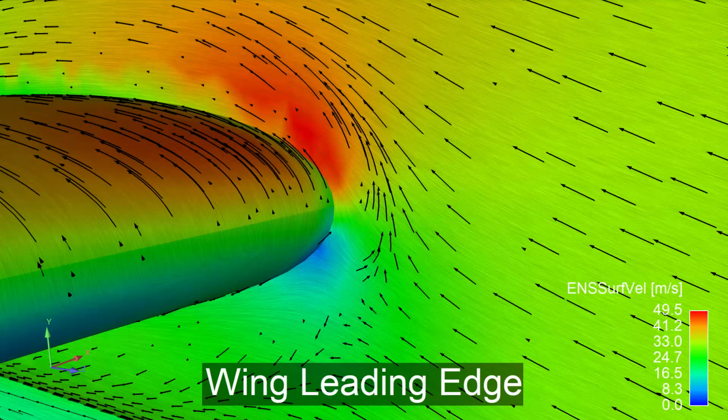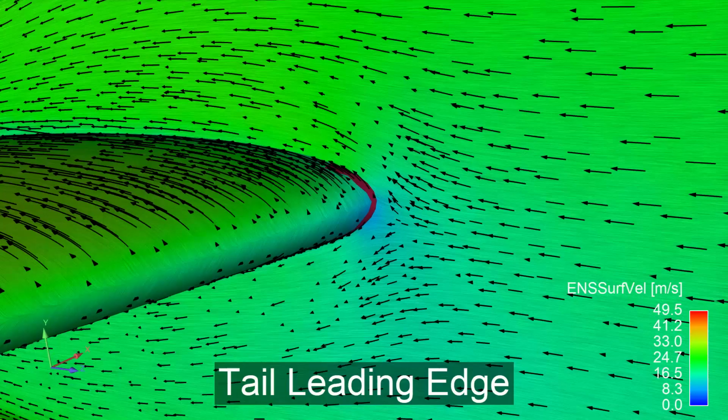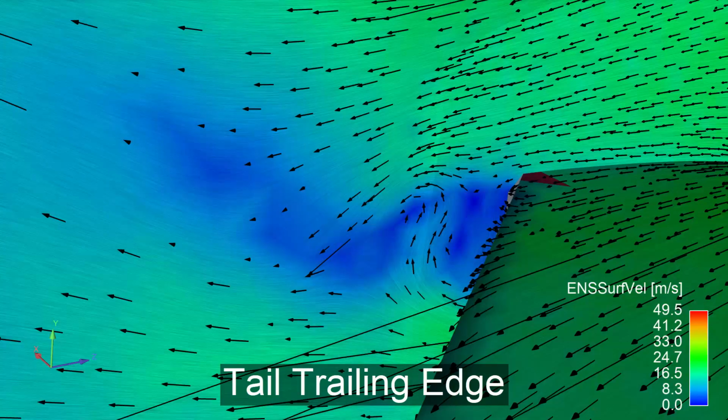I've added in a vector part showing the velocity offset onto the surface of the aircraft, and a vector part showing the velocity on the clip plane. Using both features together provides an informative visual of the behavior of the fluid in contact with the model. This concludes this demonstration showing how to utilize EnSight's line integral convolution method for fast flow visualization on a surface.